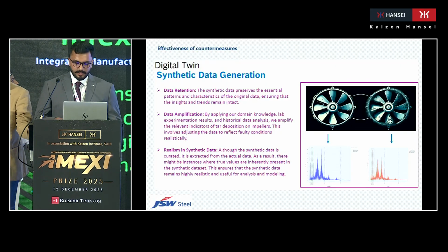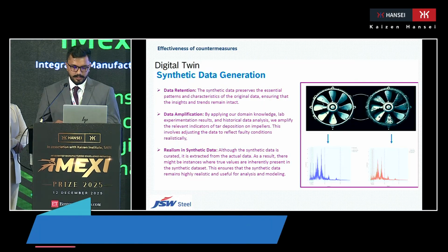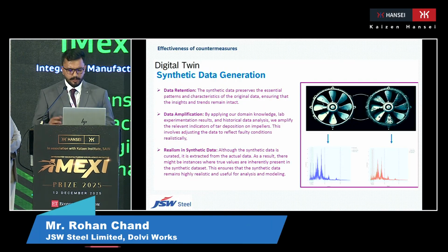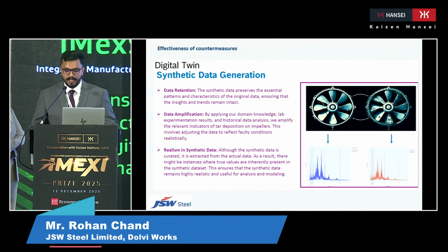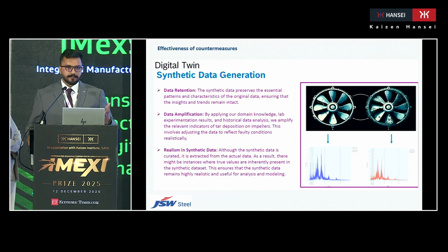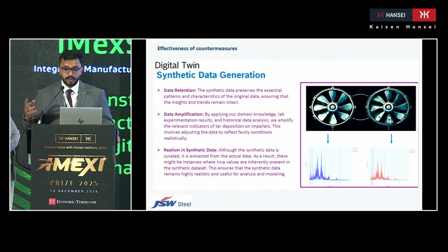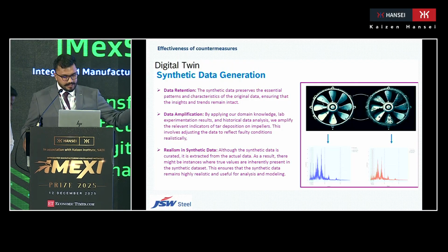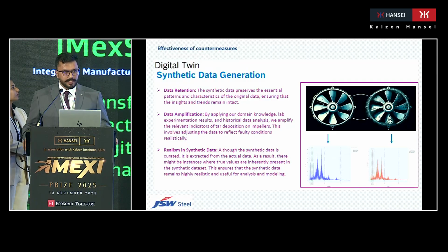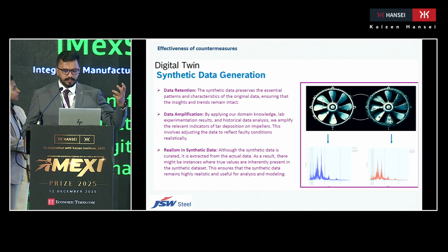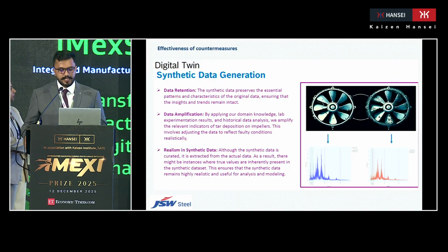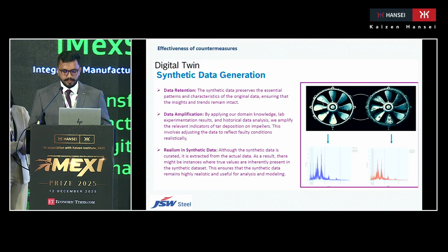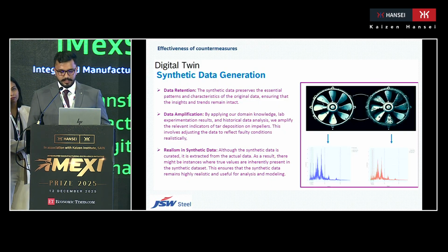Thank you, Mukul sir. So now I will be explaining the digital twin concept. A digital twin leverages synthetic data generation, which involves retaining the data collected from the field sensors and utilizing our domain knowledge of machine operations, in this case exhausters, and then incorporating this data to train various models that accurately represent the behavior of a healthy exhauster unit. The ML model we have used is a random forest classifier in the vibration analysis, and then MCSA, which is analyzing the healthiness of the motor unit.